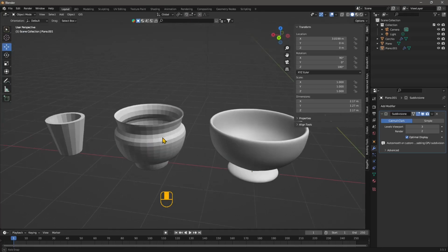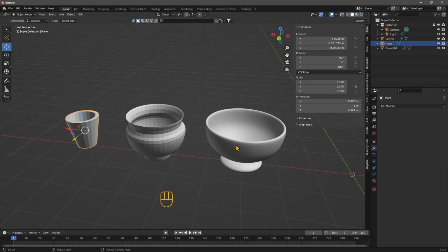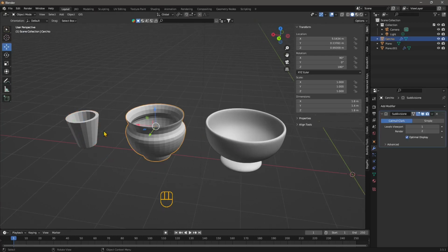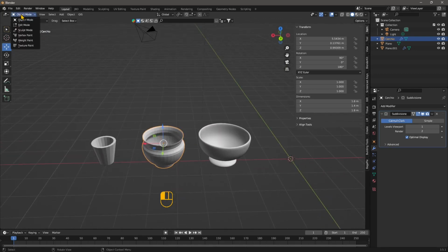In this video, we're going to talk about a specific modeling tool in Blender, which is used to create either low poly modeling or high poly modeling using the rotation of a profile around an axis. In other software, this is called the Revolve modifier or Revolution, or also Lathe or Lathe modifier in software like Cinema 4D or 3ds Max or Maya.